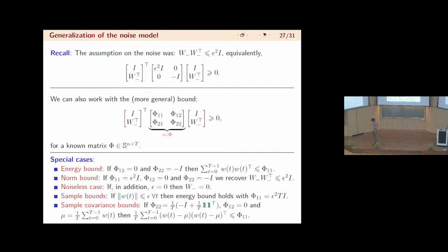But that does not mean that you obtain the same guarantees for quadratic stabilization. Because here, if we know that this linear matrix inequality is solvable, for sure we can stabilize the true system. But in that setting, since you only know that with a certain probability your noise is in a set, you lose these kind of absolute guarantees. But you can come up with statements like, with a certain probability, your controller is stabilizing for the true system.